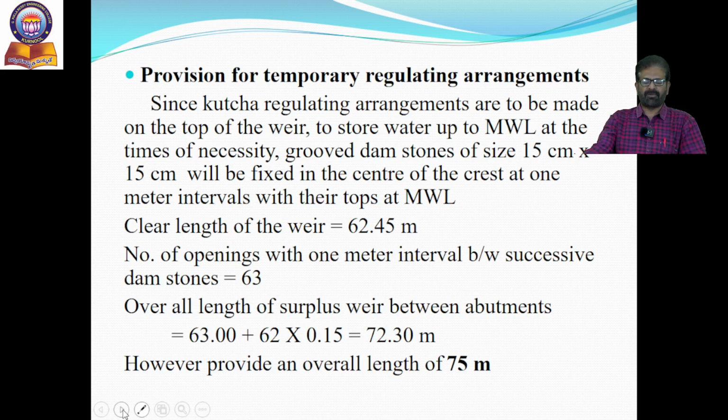In general, for providing any shutter, certain supports are required. Those supports are in the form of dam stones. Here the grooved dam stones of size 15 centimeters by 15 centimeters will be fixed in the center of the crest at 1 meter interval with their tops at maximum water level. That means the clear size of each shutter is 1 meter only. These shutters are to be provided between successive dam stones. Those dam stones have grooves, so we can conveniently operate the shutters